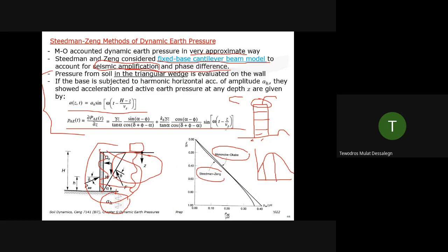That's why people designed using the pseudostatic approach in the past, even with a factor of safety more than 1, but later they realized some slopes, some dams are failing. Because seismic loading is more complex. You can't really represent it with one single value. So nowadays, the idea is to use a larger value to account for that complexity. So even if we have this, the takeaway for you is, yeah, the Mononobe-Okabe method is not that bad.